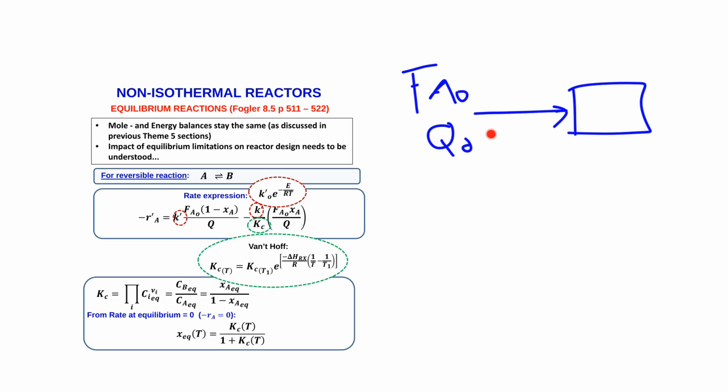What we want to do first is, for our given inlet concentration conditions with our given inlet molar flow rate of A and Q0 value, determine the maximum possible conversion in any reactor as a function of varying temperature. So we want to evaluate for a range of possible operating temperatures: how does my equilibrium conversion change? And we have two approaches in which we can calculate that.